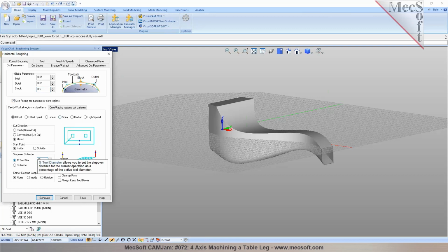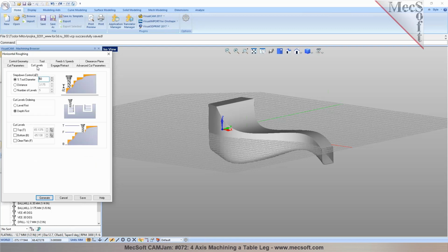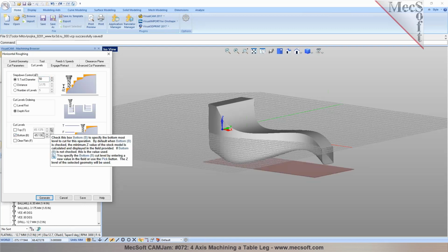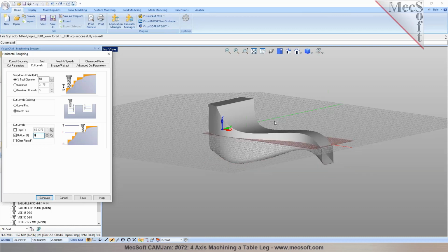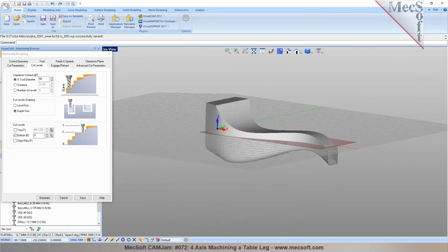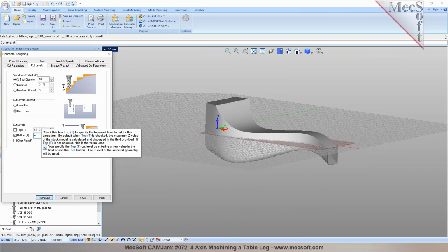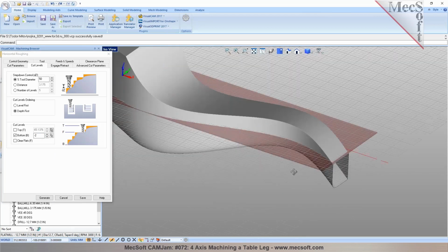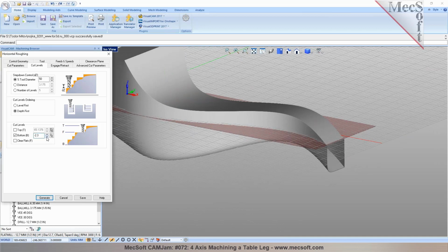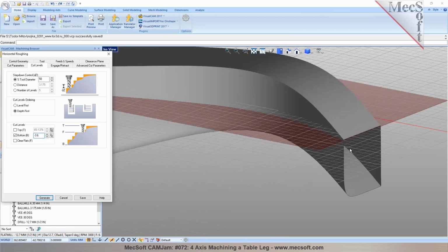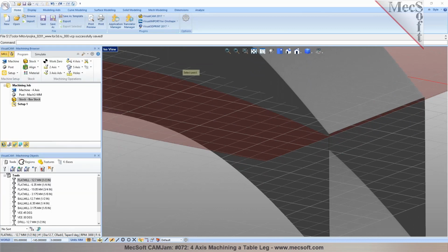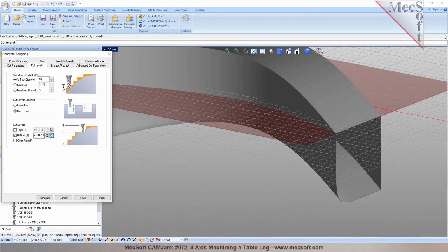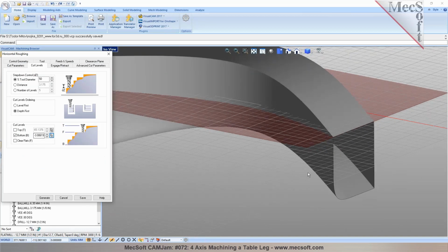Specify your step over. In the cut levels, we would want to specify a step down and probably just go halfway down. So I can specify the step down to be like a mid-plane, or I can go slightly below the midplane. I could say -2 millimeters, maybe slightly cut below the midplane. Or you can specify the value in here. You can even use the pick option in here to pick a point, and you can say you want to snap to a point near, and I can just go pick that point, and that'll determine that value is slightly over 3 millimeters midplane.